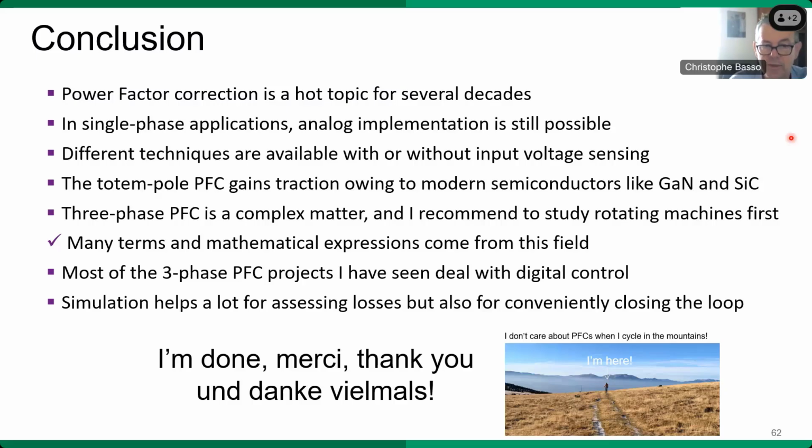In most of the three-phase PFC projects that I've seen, they deal with digital control. Honestly, there's a few analog types of control, but usually it's digital control, especially with the extra burden now asked by the utility to have a system that is able to either emulate a true resistance or add an inductive or capacitive impedance component to the load for grid regulation purposes. So usually it's done with digital control.